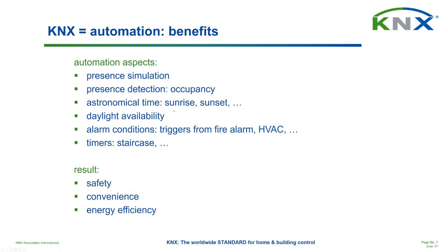Astronomical time can be involved, like sunrise, sunset, daylight availability, and alarm conditions, so that triggers come from a fire alarm or from HVAC systems. A number of timers can be used, typically for a staircase function, where the light will be switched off after a certain time.